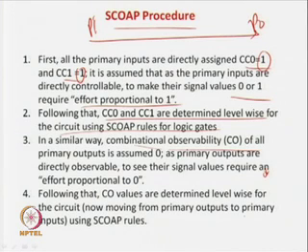But for the combinational observability CO we go the reverse way. So, we assume that the primary output lines are very easy to observe, directly if you probe you can observe. So, difficulty level is 0. So, primary input controllability difficulty is 1 and primary output observability is 0.